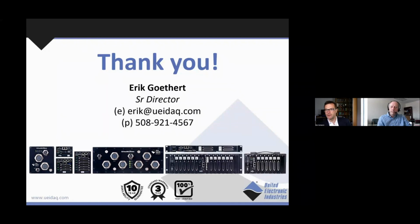Why would you want to use 429 versus 1553? 429 are direct connections between equipment, and it's an older standard. The military aircraft and the ISS use the 1553 bus so that you can have 900 devices on the bus and all be talked to in the same protocol without direct connections between the 900 devices.